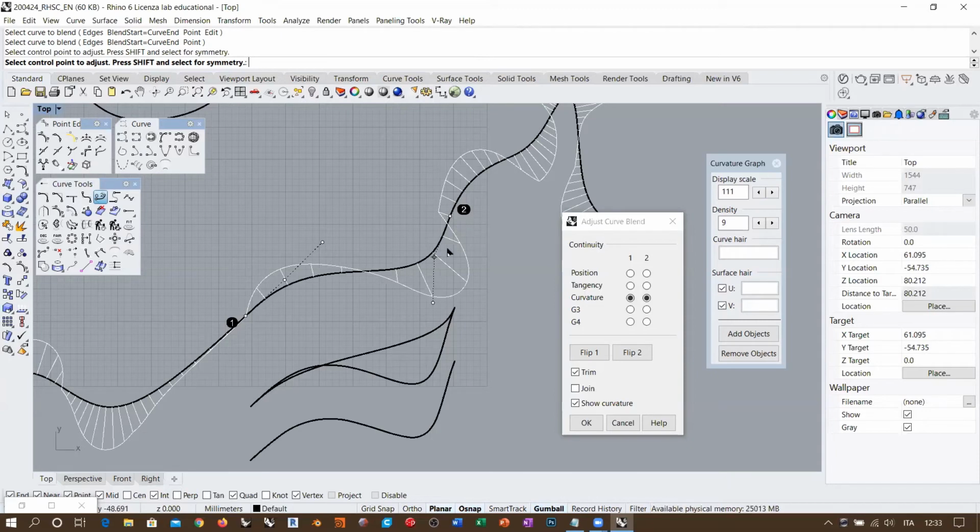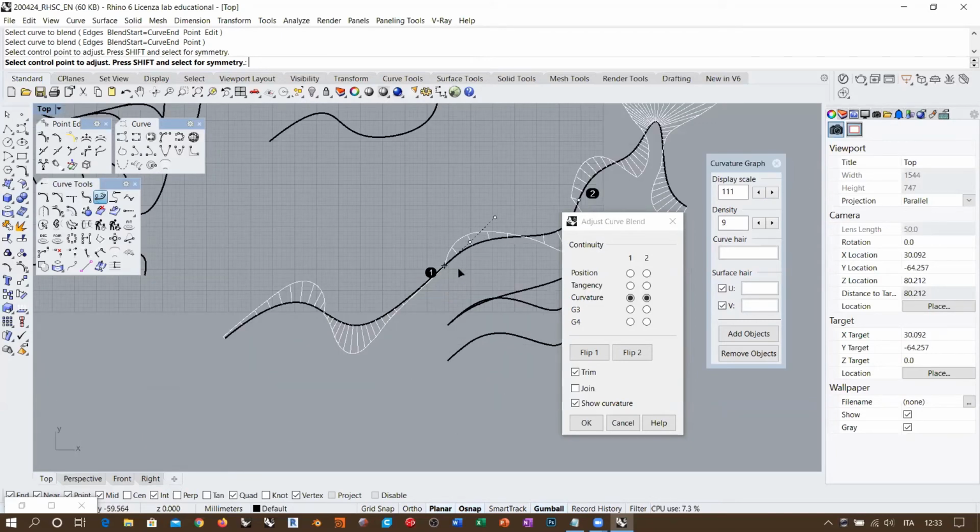As we were drawing this NURBS curve by hand, like using a control point curve, as I told you, this is a degree 3 curve. By default, Rhino doesn't create a non-uniform knot vector. And there is no possibility to create coincident control points. So there is no way that this curve here has some internal discontinuity, right?